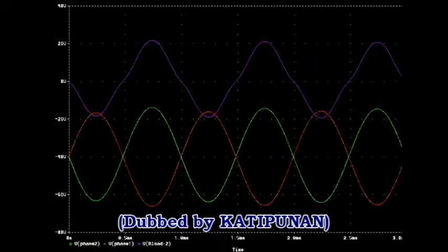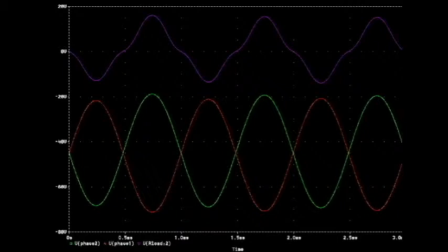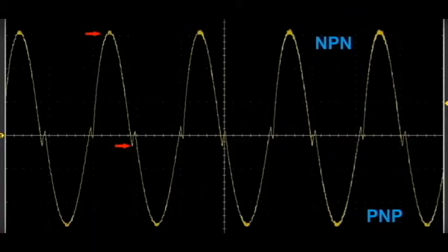A Class AB amplifier has a medium distortion compared to the other classes of amplifier and an efficiency between 25% to 79%. The push-pull circuit is biased slightly above cutoff to eliminate crossover distortion. In the case of Class AB amplifiers, crossover distortion can be reduced by using a slight forward bias in the base circuit such that the transistors are idling at a small output current. The forward bias causes the circuit to operate in Class AB mode, so both transistors are slightly on during crossover.